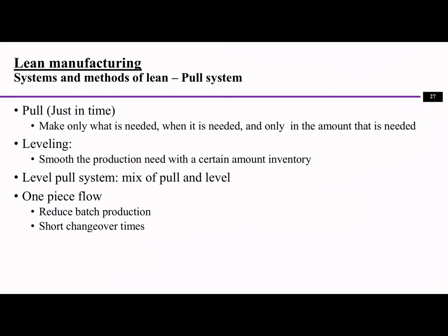Because if you reduce the batch and you have to constantly change your setups, the time for changing the setup or repositioning is going to go up, right? For example, the painting process. If I can group them into a batch of the same color, then I can just use the same kind of paint and save time.